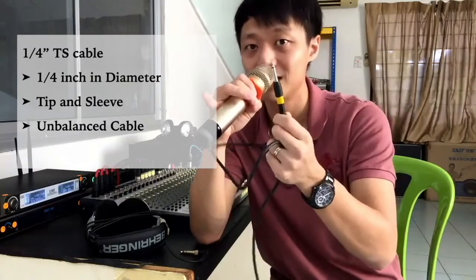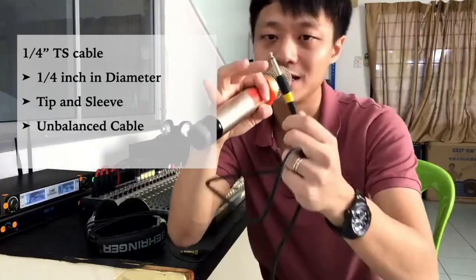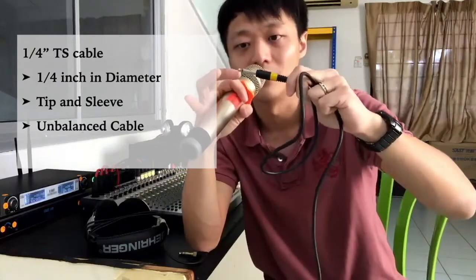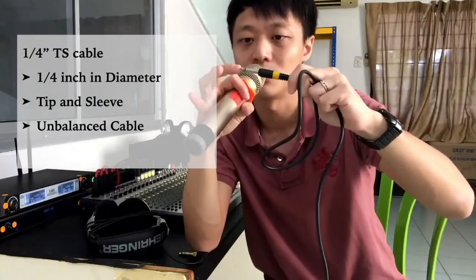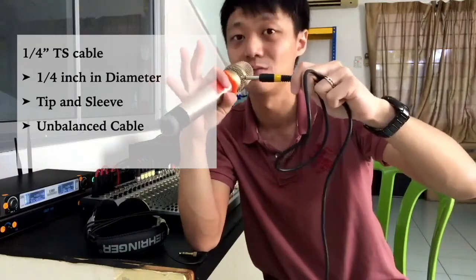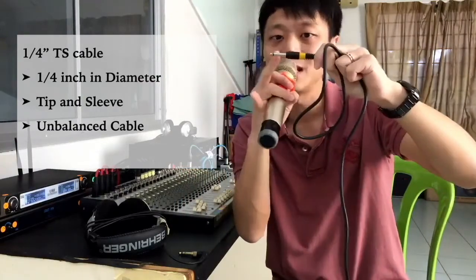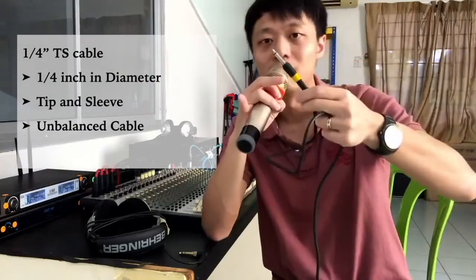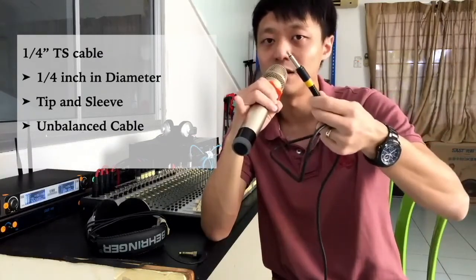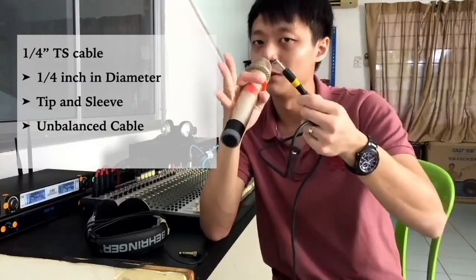Why is it called TS? T stands for tip and S stands for sleeve. As you can see, the metallic part at the tip can conduct electricity, so it can carry audio signal. The T stands for the tip here, and the S stands for the sleeve. So the TS cable can carry unbalanced mono signal, just like the RCA. So the RCA can carry unbalanced mono or stereo signal depending on how many you use.